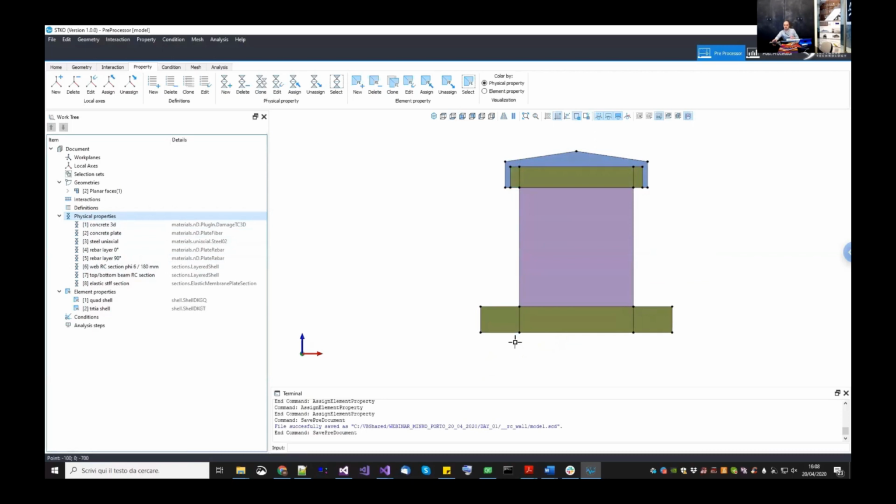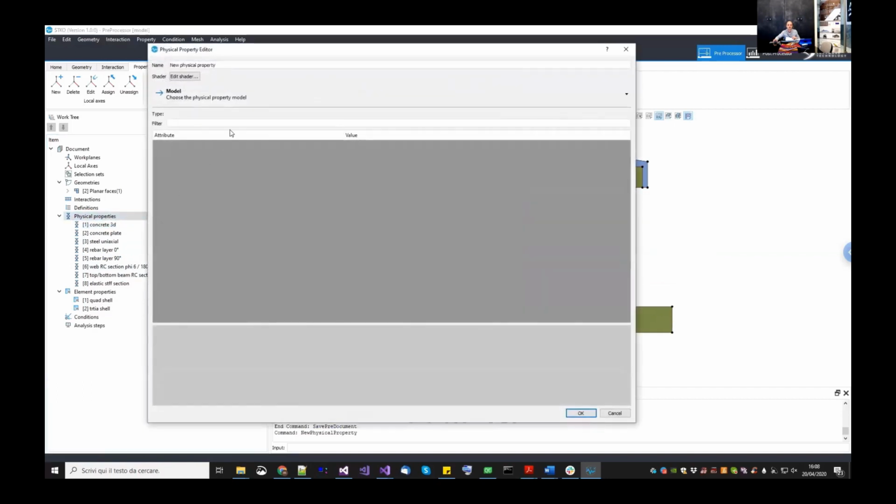Now, since we are going to model the beams as a nonlinear distributed plasticity model, we need a fiber cross-section. So let me see the dimension of this fiber. And of course, since we need to do a fiber cross-section, we need a uniaxial material model, which has pretty much the same material parameters of this one. It was slightly different in the paper, but let's keep it the same.